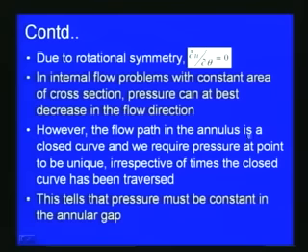However, the flow path in the annulus is a closed curve and we require the pressure at a point to be unique irrespective of how many times the closed curve has been traversed. So, these are the assumptions which we use for this problem. This tells us that the pressure must be constant in the annular gap.